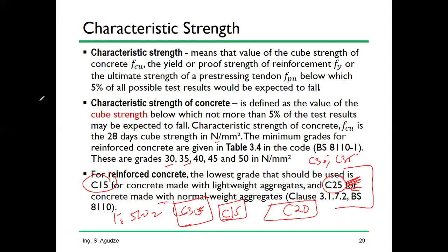We call something ratio and design strength. So if I specify that C25 must be used for the concrete, it must remain C25. And you must find a ratio which we call design mix. So you have to do a preliminary mix design and get the ratio that can give you C25.